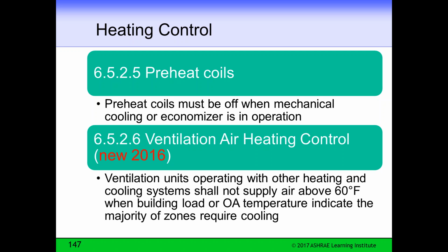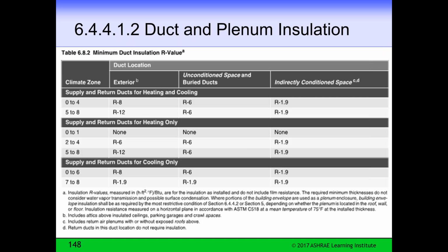We feel that it's wasteful to try to bring that air back up after you've dried it out. The same requirement is applied to outside air that's supplied from the DOAS system to the back of the air handling unit itself. If we keep it cooler, it'll back off some of the energy used by the air handler.